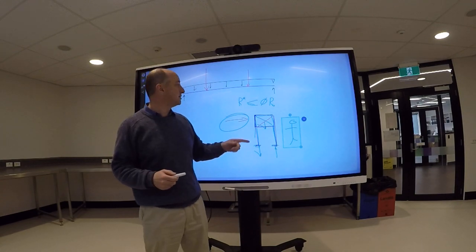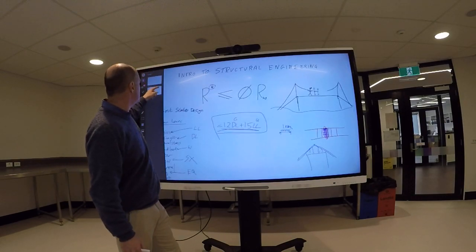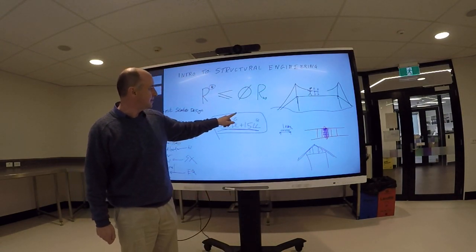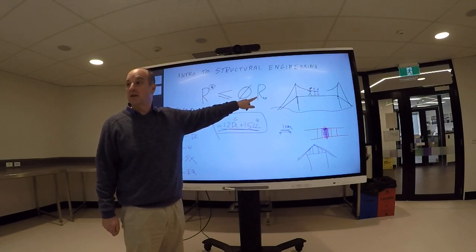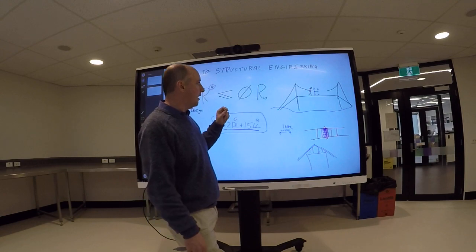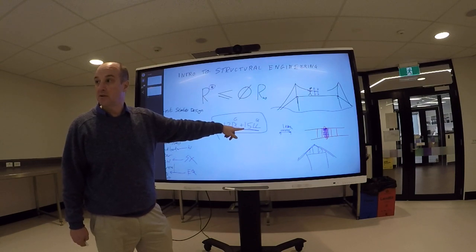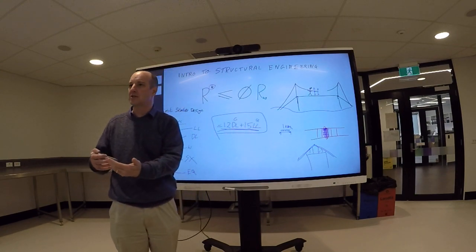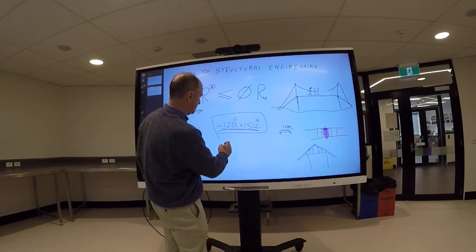All right, so the key points, the factor of safety. If someone asks you what is the factor of safety, it's not easy to give a really straight answer because the factor of safety is both in the way we exaggerate the loads and the way we slightly underestimate the capacity. All right, those two multiply together to make the factor of safety. The other thing, oh yes, I should have mentioned, when we consider serviceability, we don't exaggerate the loads. And that's because we want to know how much the thing is going to deflect under the actual load, right?